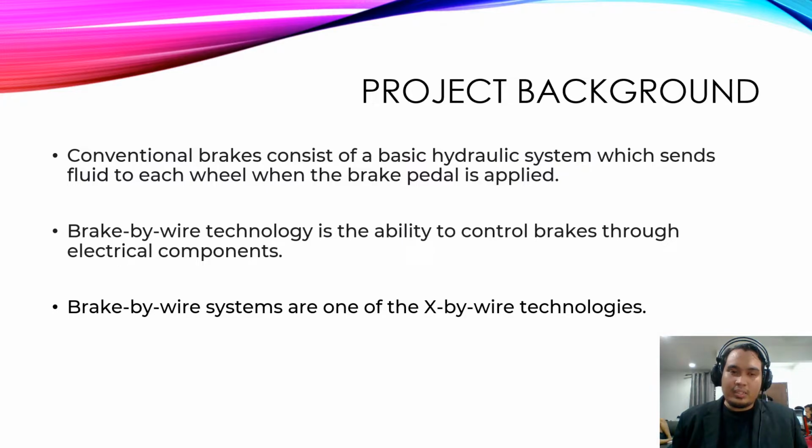So the project background is the conventional brake consists of a basic hydraulic system which sends fluid to each wheel when the brake pedal is applied. So brake-by-wire technology is the ability to control brakes with electrical components. Brake-by-wire systems are one of the by-wire technologies.